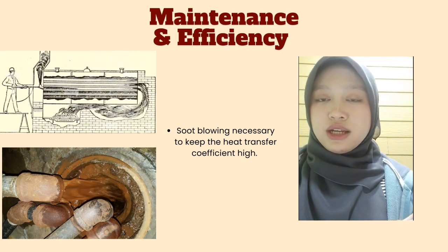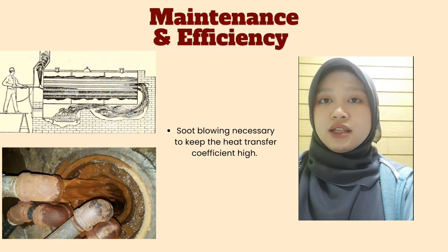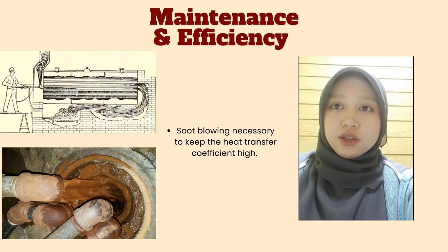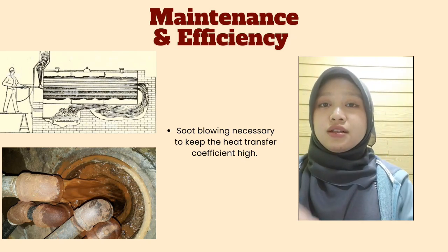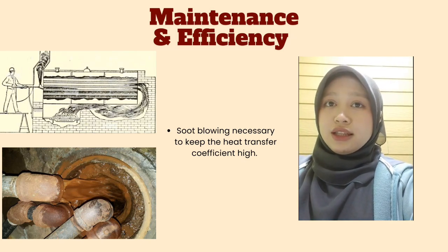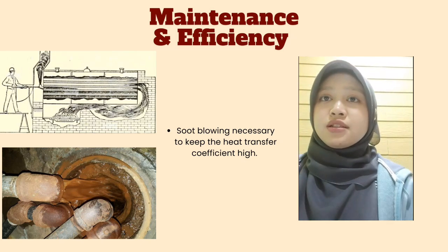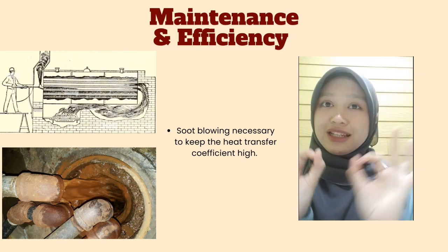On the water side, as we discussed, scale from impurities is a killer for conduction. The process of blowdown, removing water from the bottom of the shell, helps control the concentration of suspended and dissolved solids, preventing scale formation and ensuring the tubes remain thermally conductive.